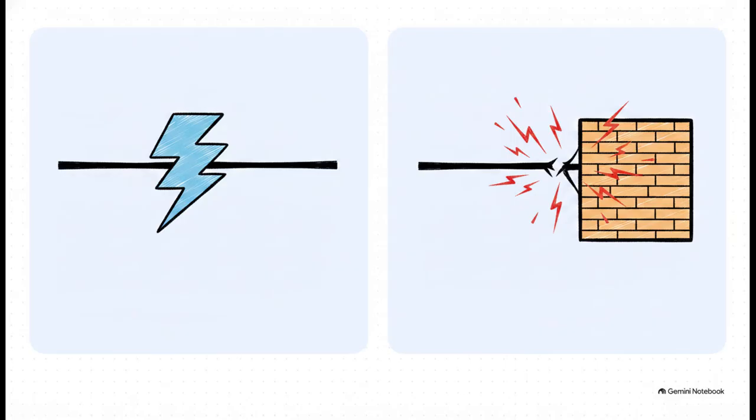And this brilliantly illustrates the rule of opposites. In a series circuit, hitting that resonant frequency means your impedance drops to essentially zero. It acts just like a short circuit, causing massive voltage magnification. But on a parallel circuit, the exact opposite happens. Impedance absolutely spikes to infinity. It acts like a fully open circuit, which leads to massive current magnification. It is a night and day difference. And getting the two confused? Yeah, definitely not an option.